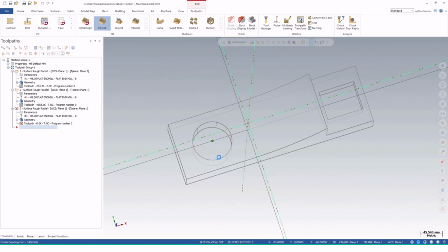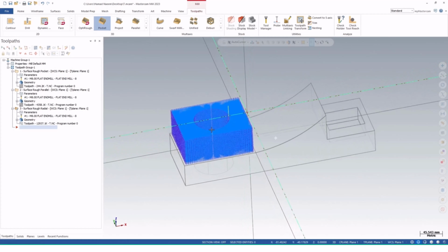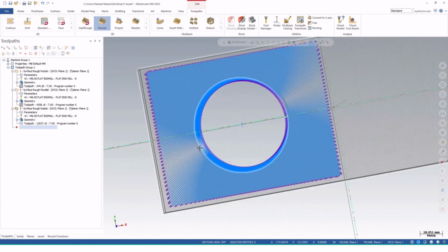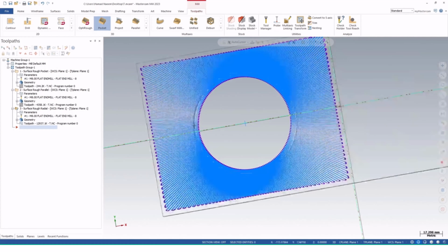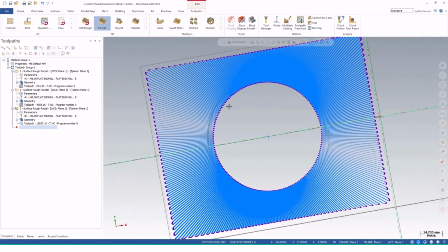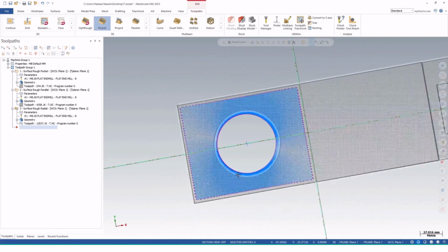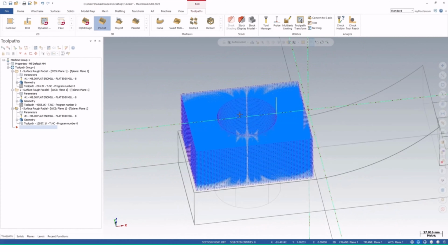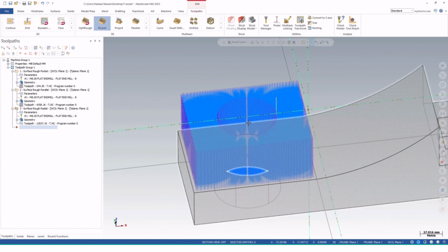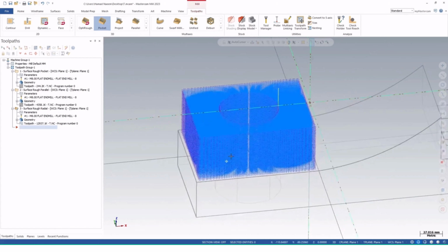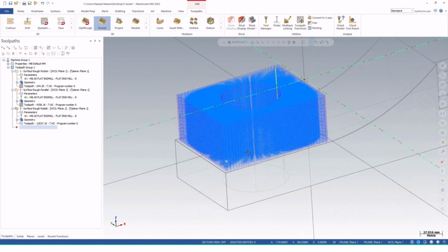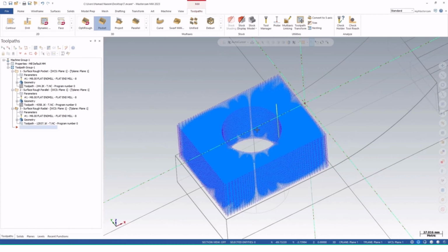So we have defined the center point, and see here the cutter will work in a radial position, just like the clock works. Okay, so it will be at a 1 degree cut. To take every 1 degree cut and take an offset of 1 millimeter and cut the whole thing. Okay, so it will not remove any material inside that area. So this is how our radial surface rough surface works.